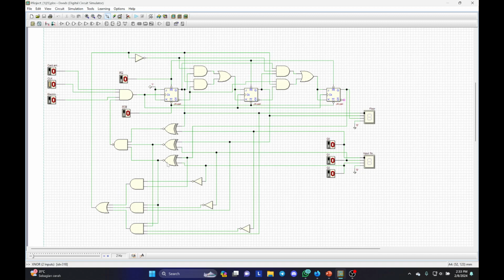And when the output of section A and section B is the same, the XNOR gate will output 1 and the AND gate will output 0, so that this AND gate that serves as our clock enabler will output 0, essentially causing our circuit to not operate, indicating that the lift's current floor and the inputted floor are the same.